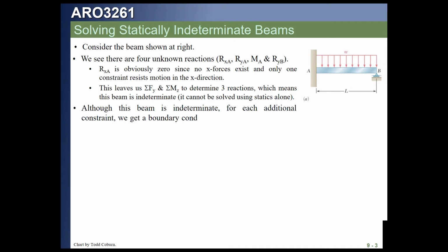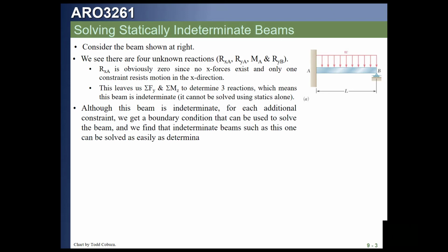We're going to find that the easiest way to solve this is writing singularity functions for loading, as we've said before. In fact, if we look at our beam again, having written the singularity function, we're going to impose the boundary conditions. Our boundary conditions, we see the left end. That wall imposes no deflection in the horizontal or vertical directions, and it means that the slope at point A must be 0. Similarly, the deflection at B, the vertical deflection, must be 0. And we're going to utilize this to solve.